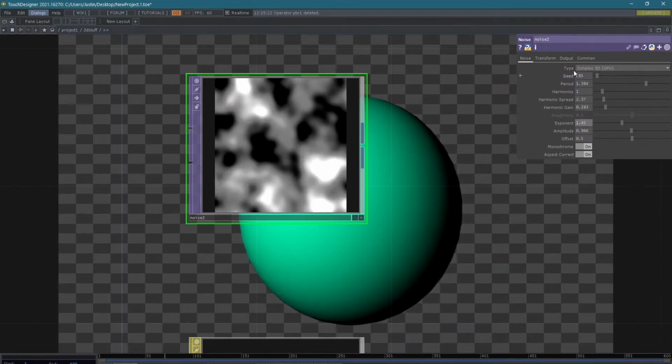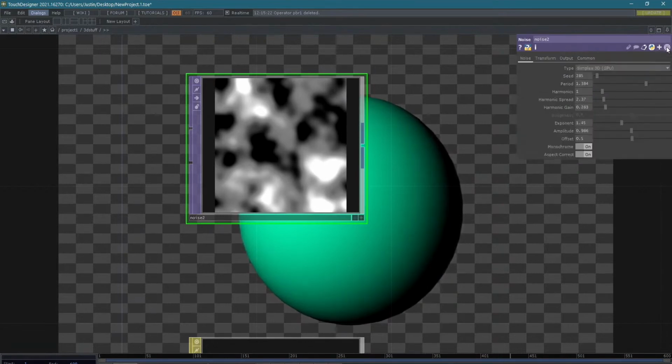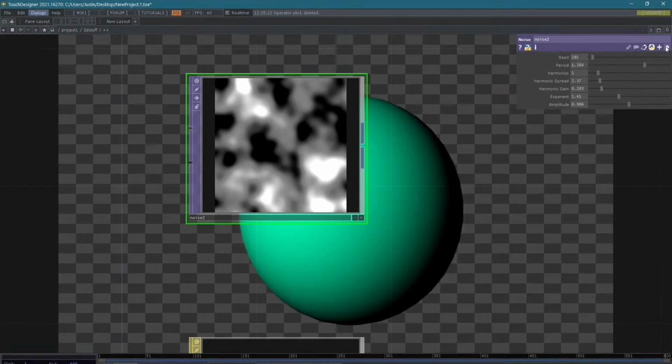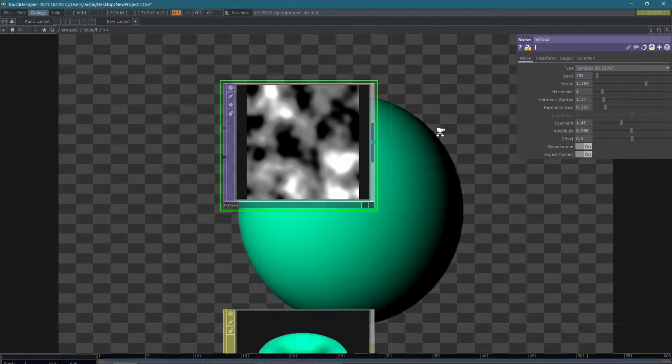Another thing about the interface: if you're messing with this whole set of options and you've lost track of what you've changed, this little target here at the very corner, if you click it, will condense down to only the options that you've changed. All the defaults will disappear, so you can see exactly what you've changed. That's handy when you get lost, especially when you're 30 parameters into messing with something. Of course, if you go too far off, you can always delete it, re-add the operator, and work from there. All the operators generally have the same presets.